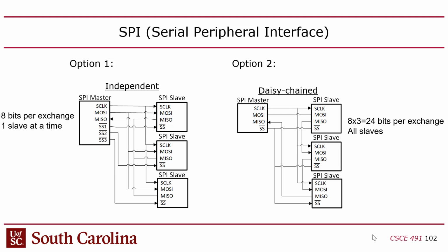Those bus modules, or those interconnect modules that serve as intermediary, that's really what enables there to be multiple masters in Avalon. And in SPI, there's just no way. There's no way to do it. You can have multiple slaves, but even that's tricky.